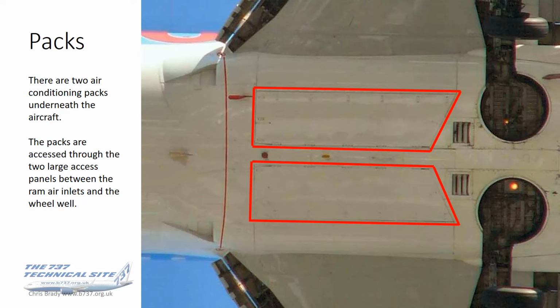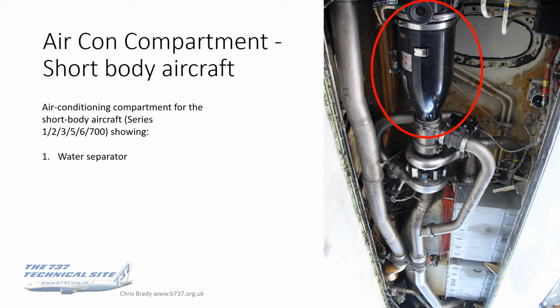Okay, so let's take a look at this in a bit more detail. The two air conditioning packs are located underneath the aircraft in the locations I've marked there in the red outline. Those packs are accessed through those two large access panels that sit between the ram air inlet and the wheel well. Opening either of those panels, you will see this. That is the air conditioning pack itself.